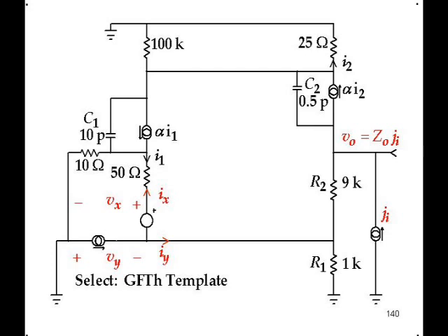Now for voltage feedback, the H infinity term is 0. That's for gain, voltage gain, that's the important one that you want. But for output impedance, it's 0. Why is that? Because we know voltage feedback lowers output impedance. If you have infinite loop gain, the output impedance goes to 0.